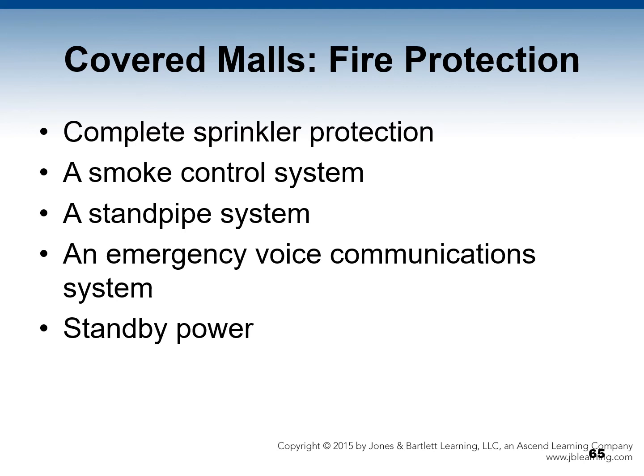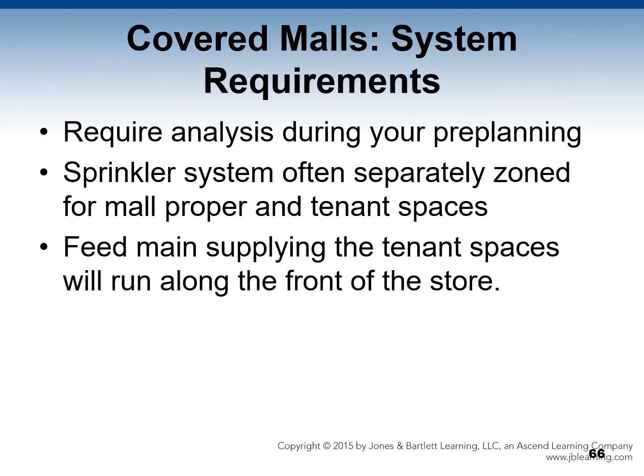In terms of fire protection in malls, they include complete sprinkler protection, a smoke control system, a standpipe system, an emergency voice communication system, and standby power. System requirements involve required analysis during your pre-planning. So we talked a lot about pre-planning in other classes and in previous chapters. But covered malls require analysis during your pre-planning.